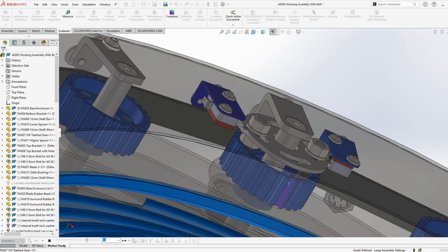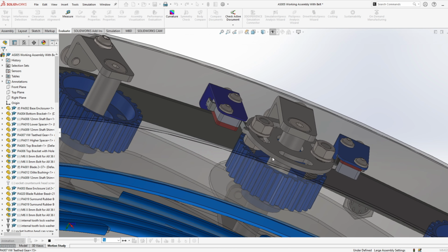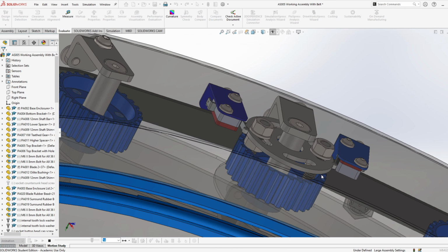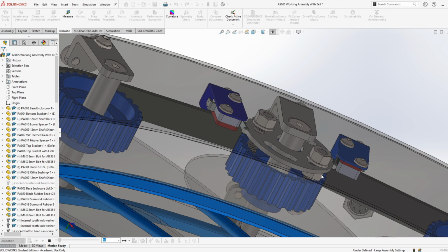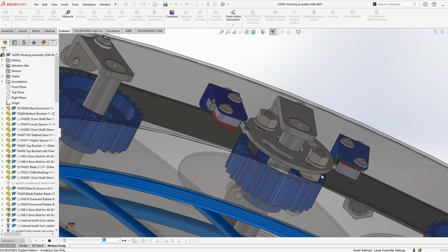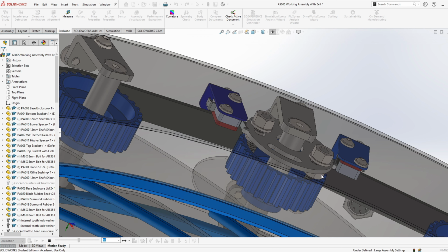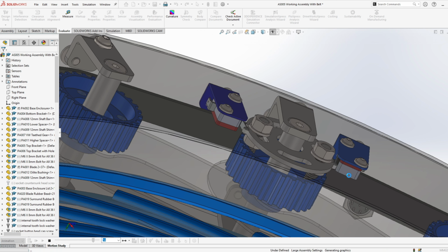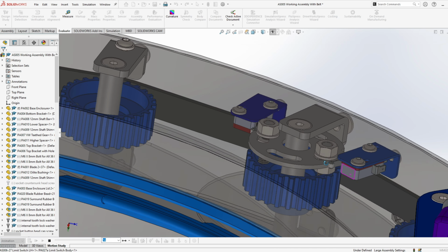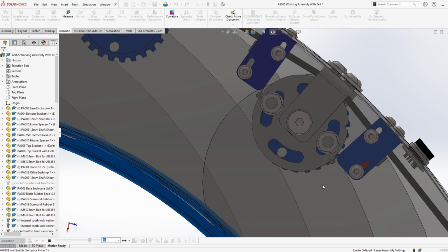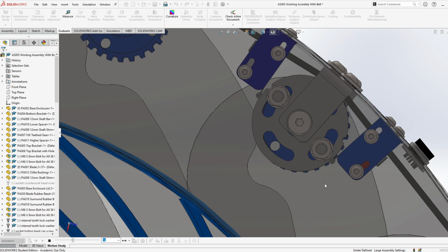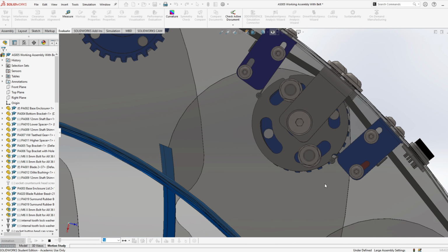I'll zoom in nice and close. And it's also fixed using 4 washers and 4 nuts. So this allows fine adjustment of both height and the angle of orientation. If you focus in on this detector plate even more here, you will see how both roller levers of the switches align up with the 2 notches in both its open and closed state.